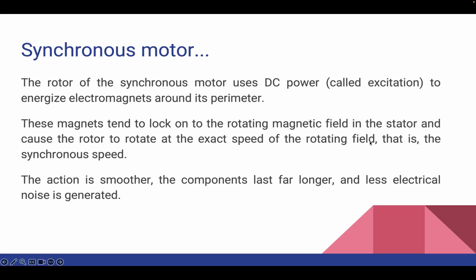Now, these slip rings and brushes may sound a little familiar, as they resemble the commutator assembly used in DC motors. And there is a key distinction: in a synchronous motor, the electrical contact from the stator to the rotor is made through smooth rings rather than the multiple contacts found in DC motor commutators.